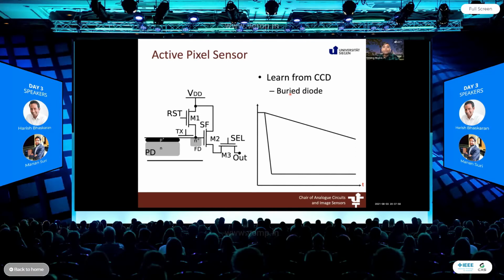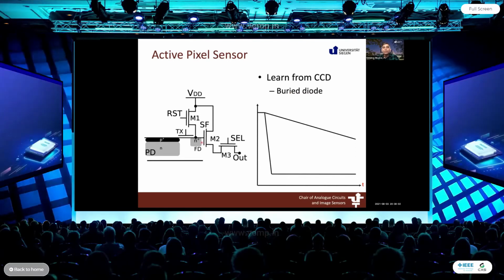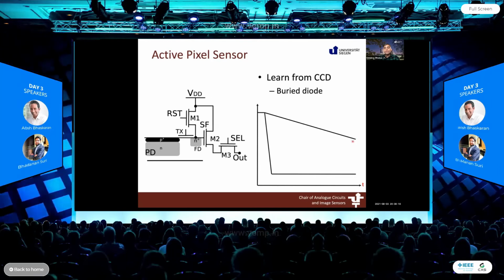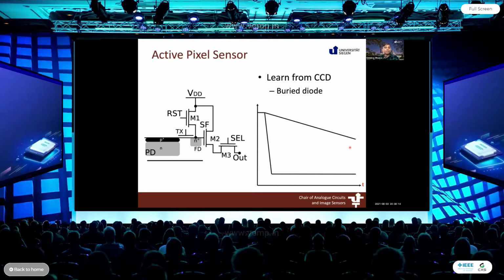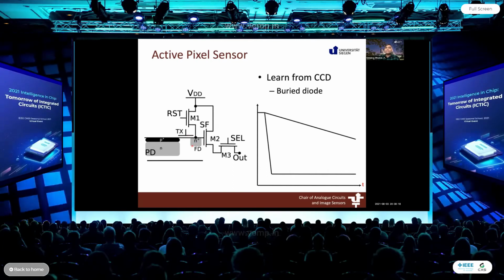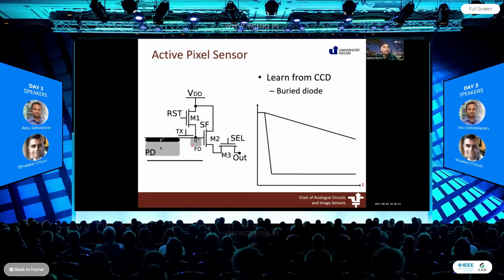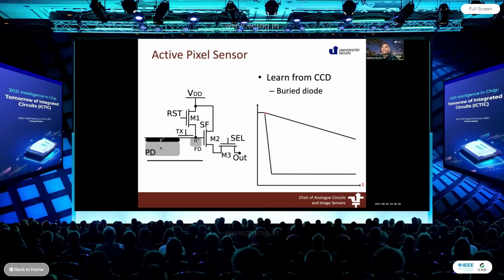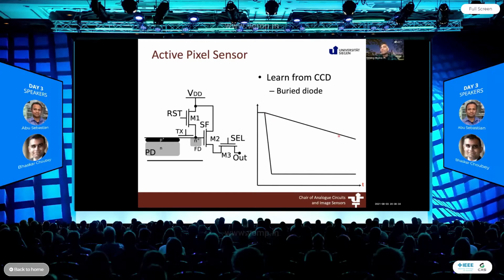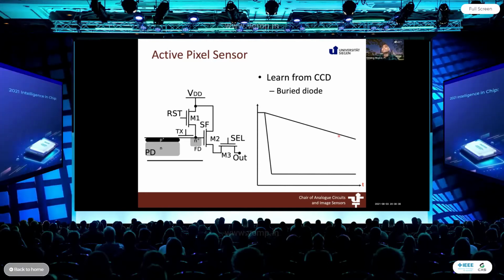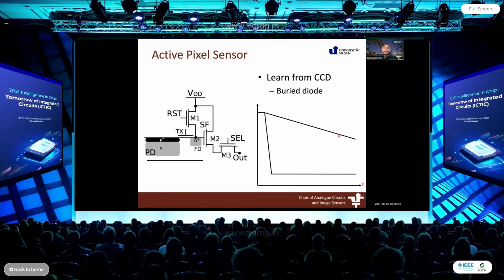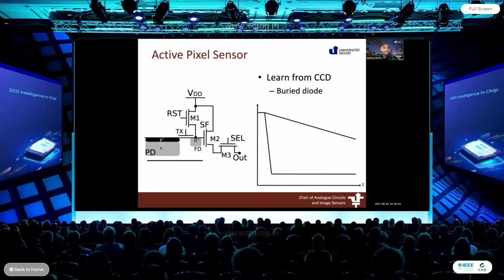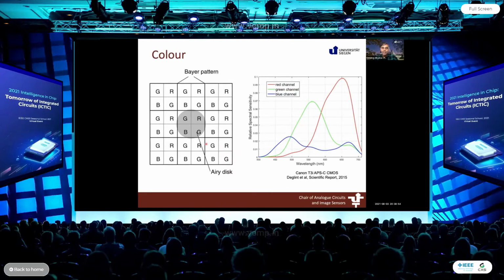Those who have done image sensor courses would know that we actually learn from charge coupled devices, and we have a floating diffusion inside the pixel. So we store the reset value as well as the integrated value after a certain time, and take the difference between these two. If you take the difference, you are going to remove all the additive noises. So all the fixed pattern noise due to additive offsets will be removed. And if you also store the reset noise at the beginning of integration, that noise during the course of integration should not change. So you'll also be getting rid of much of the thermally generated reset noise. So kTC noise will go down as well. We do this already, and this floating diffusion takes area inside the pixels. So we are having a lower and lower fill factor of these pixels, which we don't like from an imager designer point of view. So that's the pixel part.